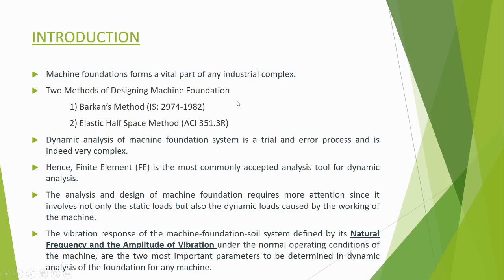In Barkan's method, the embedment effect and the soil damping are not considered, whereas they are considered in elastic half-space method. But as it is recommended by Indian Standard Code, we are going to model the machine foundation using Barkan's method. And dynamic analysis of machine foundation system is a trial and error based process, and it is very complex. Hence, finite element is the most commonly accepted analysis tool for dynamic analysis.